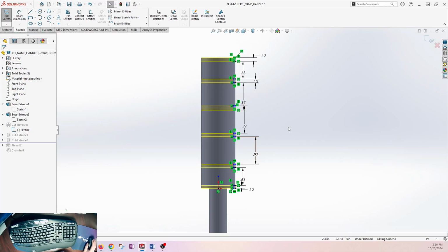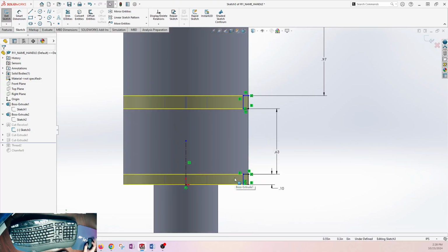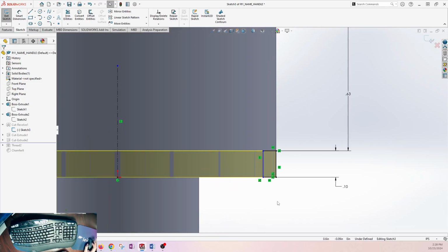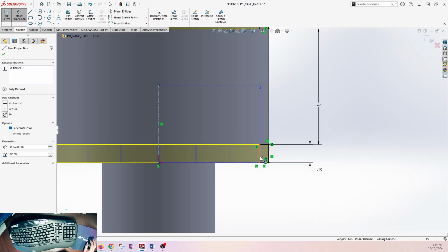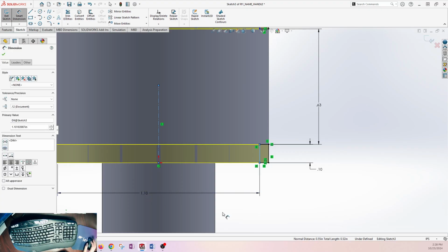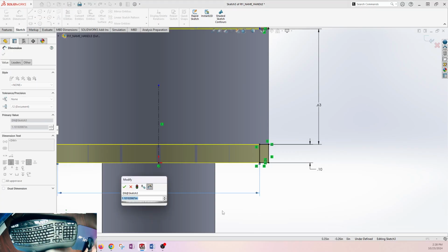With feature-based modeling, we are not supposed to be lumping a bunch of stuff into a sketch. And also, we need to fully define our sketches, right? So maybe you wanted to start with that first one. It's pretty easy to measure a diameter, so you could have measured the diameter and put that dimension there. And see, that's all kinds of digits which we can't even measure, but we could definitely measure to the 1.102.